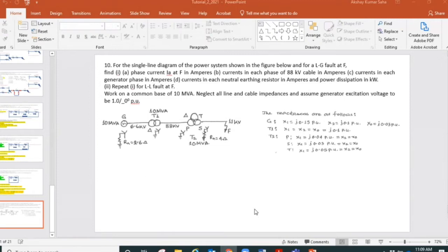Now the first harmonic, or the fundamental one, is the highest one. So if you consider the whole waveform as 100%, you will get, let's say, 99% from the fundamental. We can also find out using Fourier transformation not only which frequencies are present, but how much of each frequency is present in that waveform.